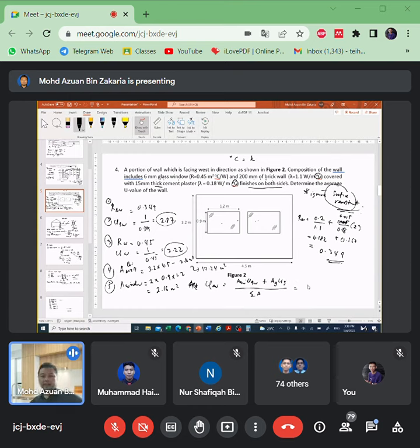So we have for brick wall, U brick 2.87, area of brick 12.24, plus U A for the glass, which is 2.22 times 2.16.